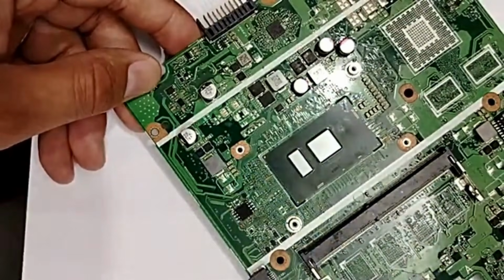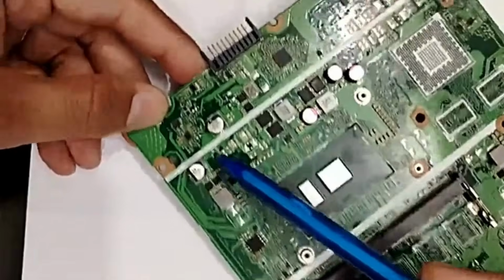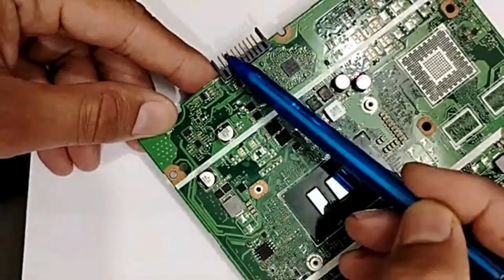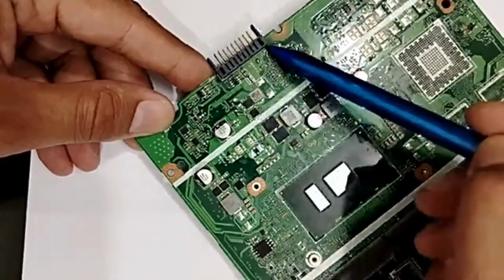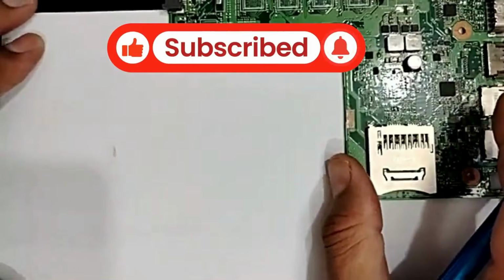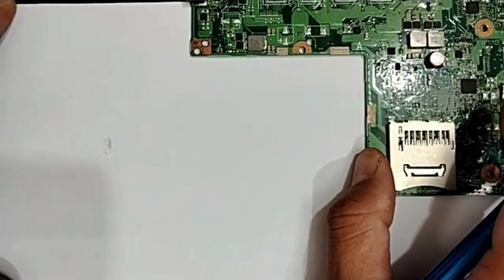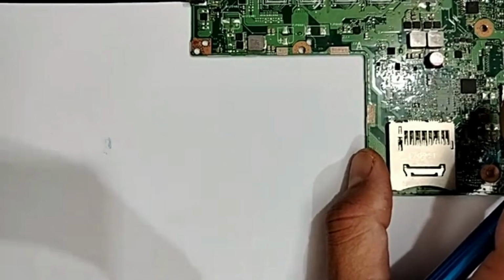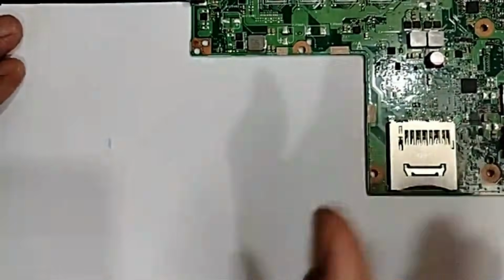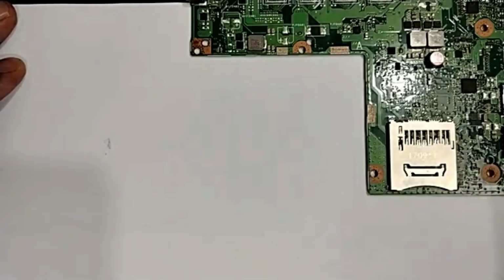Guys, I teach you how to locate and identify the circuits, just use your eyes. Here we have an isolated inductor near the battery connector, means this is for the battery connector. Okay, guys, now if you understand this video, you can fix any short circuit in the world, any short circuit in any motherboard, because I will teach you the process. Okay, any short circuit, regardless of the kind of short circuit.